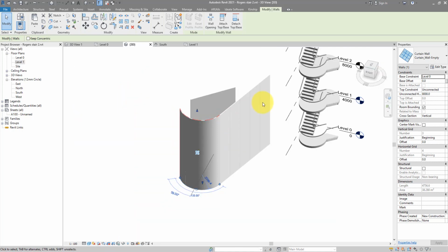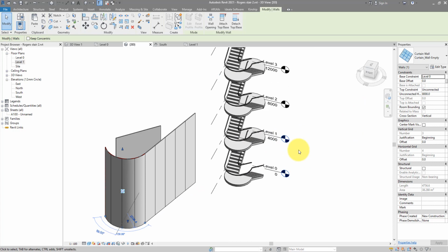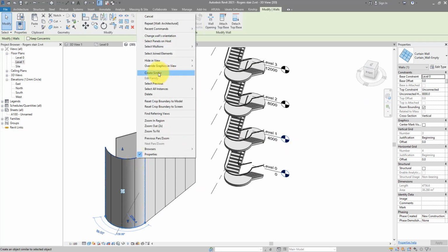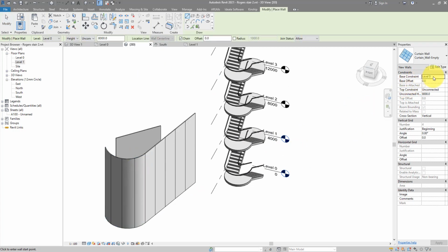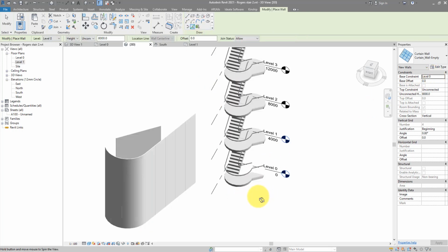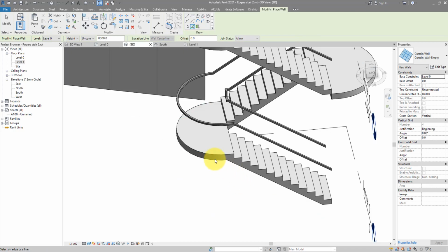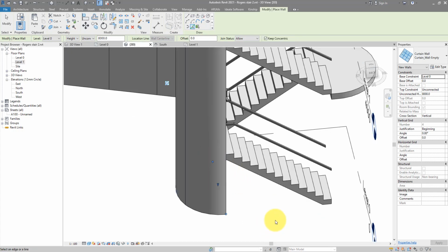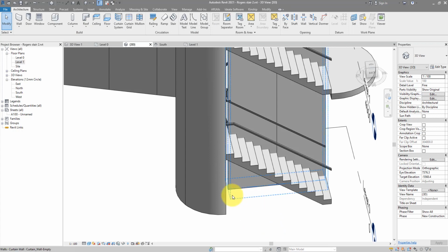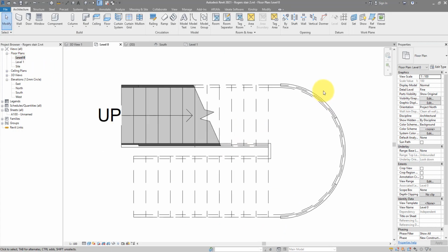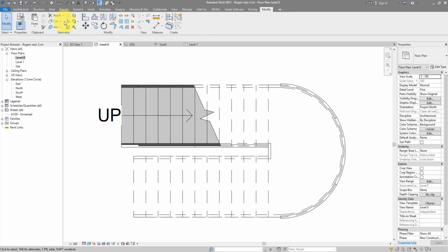It's time now to use this wall type and wrap around our staircase. Let's do right click on one of them and do create similar. Make sure the level for the base is correct. And then you can use this pick line button to start creating walls. I will go around this and start from here. To begin, we only need 2 of them, one curved and one straight. Let's now return to the level 0 view, and here's our curved ones. I can see now that the panels are clashing into my stair. Let's offset them away slightly. Go to offset, and let's try 50 mm.